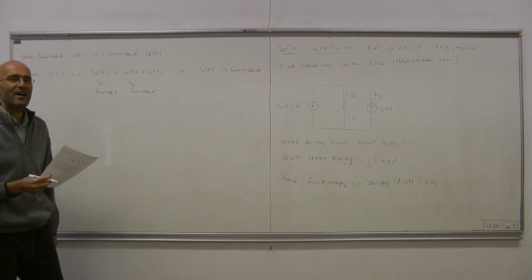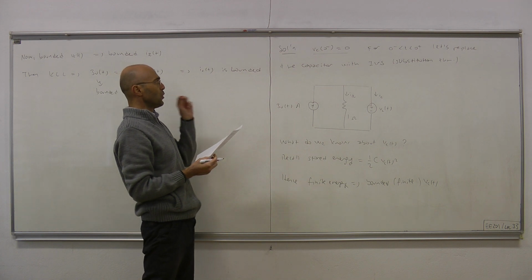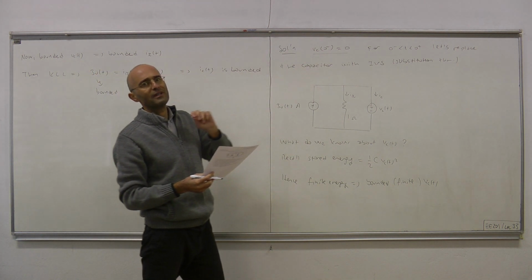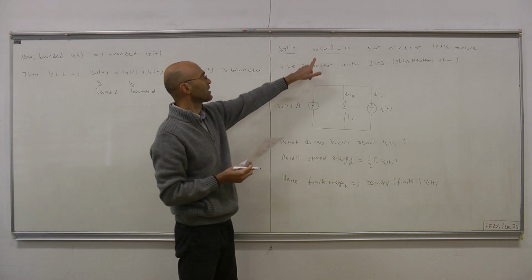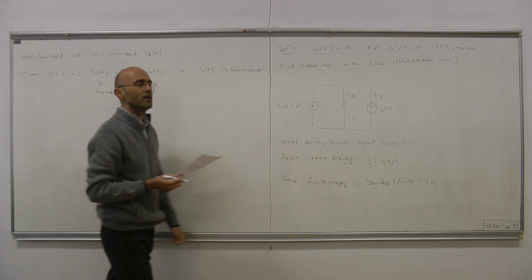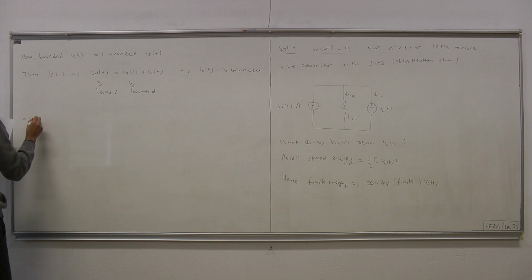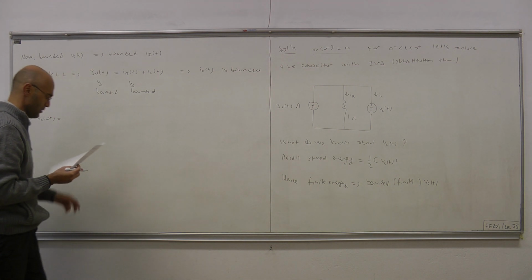And that's the only thing that we have to know in order to be able to determine whether the capacitor voltage will experience a discontinuity or a jump at t equals 0, or at any time. It's easy to see once we write the terminal equation for the capacitor.